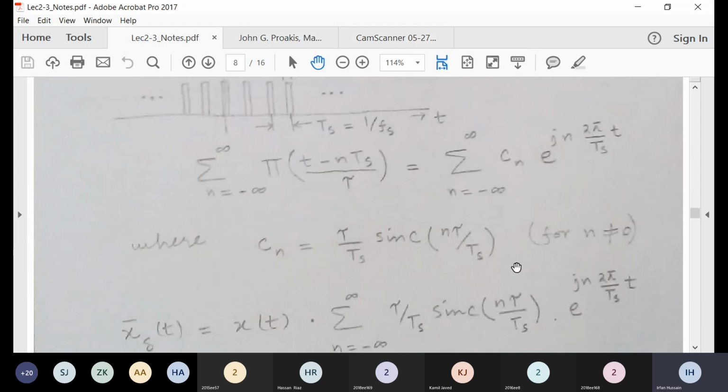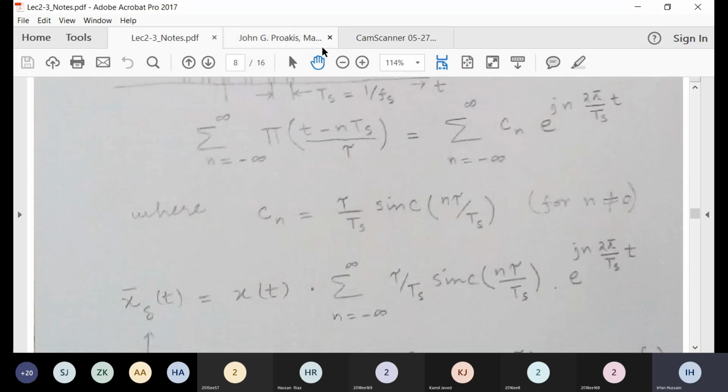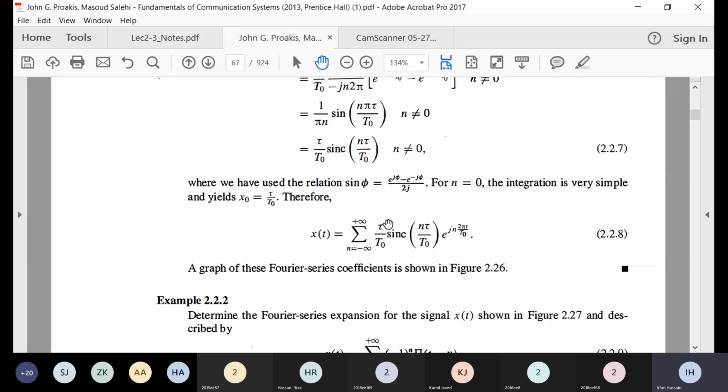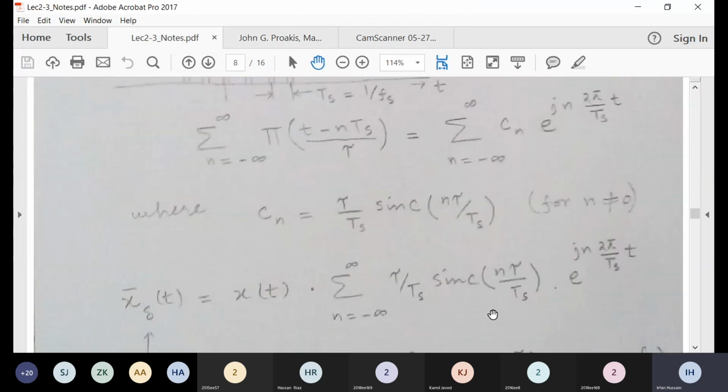So that is why I am multiplying my signal not by an impulse train but by a train of rects, and we just saw that those train of rects could be given as follows. So I just write this there. Alright. This will also cover for n is equal to 0, because for n is equal to 0, sinc of 0 is 1, and you will be just getting again tau over ts, because the width in time is 1 over ts.